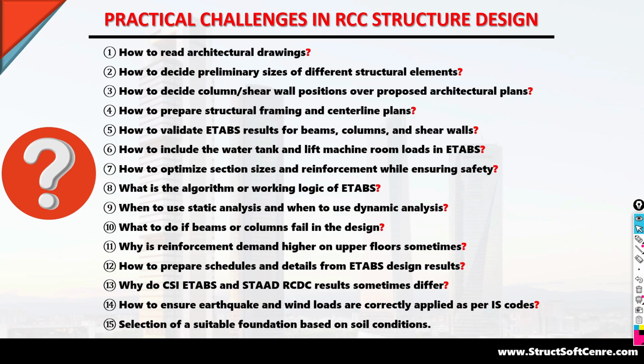People are asking, sir, we are going to deal with a G+2 floor building and the size of the column required is 230 by 800 mm. It is totally unpredictable and unexpected. It is not required for a G+2 floor residential building, 230 by 800 mm size. It is not possible at all.